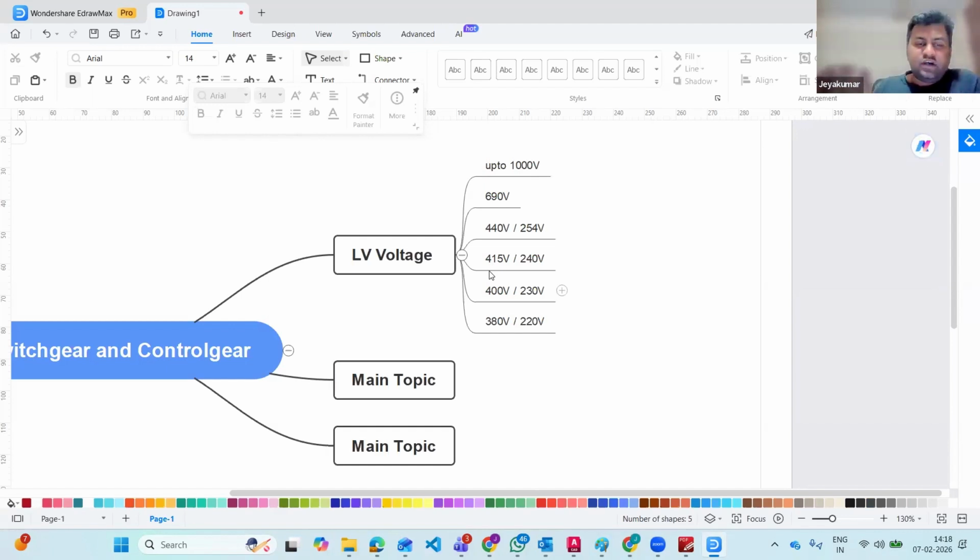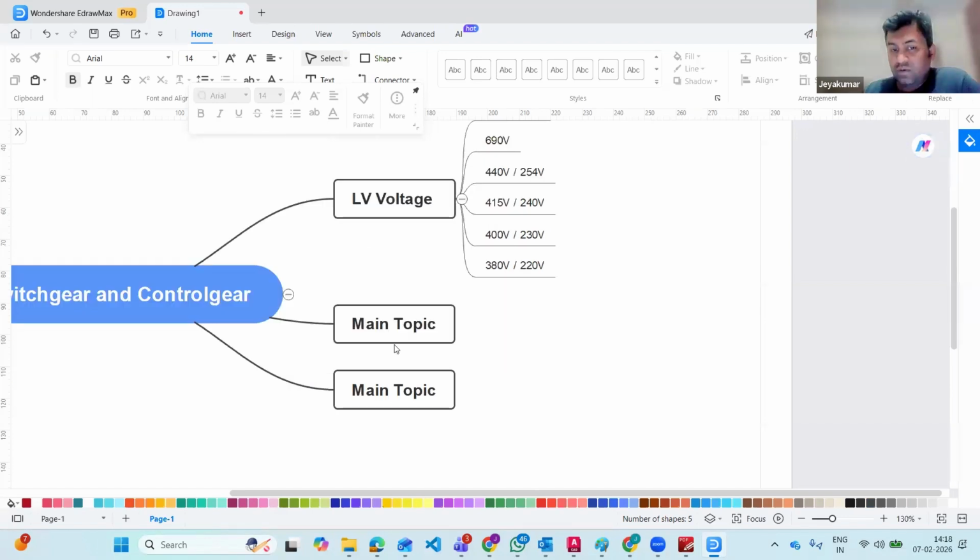But as per IEC, the rule states that anything beyond 1000 volt goes high voltage. But when it comes to the DC point of view, maybe in solar, up to 1500 it is there. So based on that, when you size cables and so on, you need to consider some insulation according to the voltage level that you are putting in. Okay, that is what you need to look into, because some of the inverters are operating in that voltage range. That's what is trending in the market, right? That is one thing.